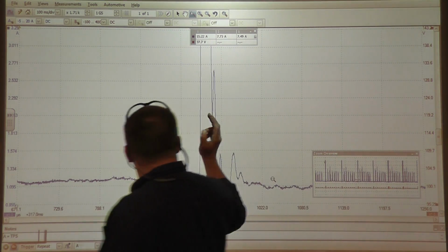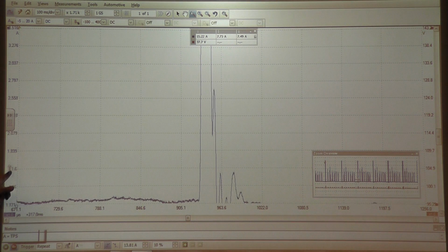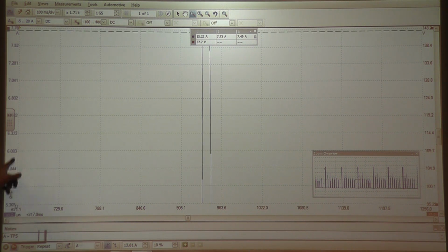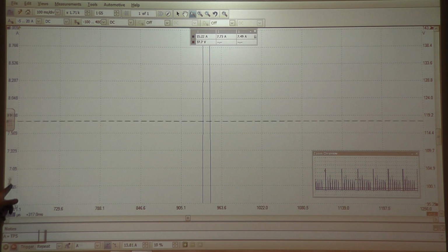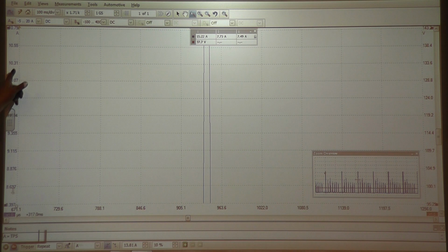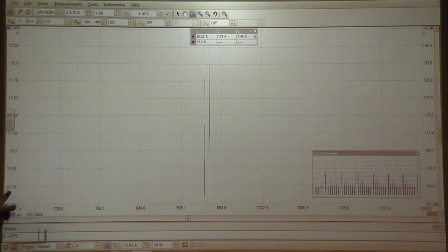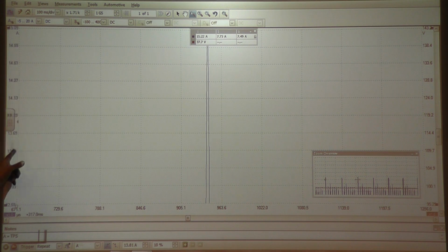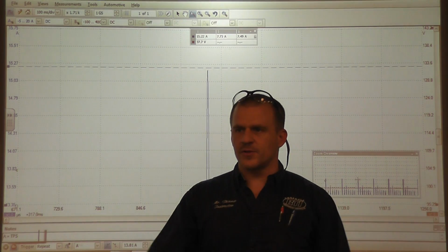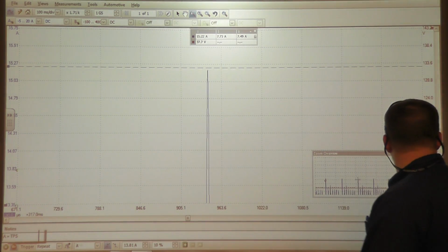Should coil current ramps have straight up lines? In my book I cover this, that a current ramp pattern should never have a straight up line. That is clearly no ramp at all. This is a seriously zoomed in view of this spike. There is no ramp there at all. It is a straight up line. Very small dwell time. The computer's trying to protect itself.